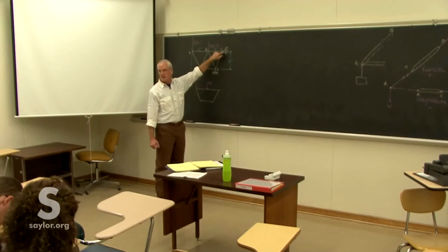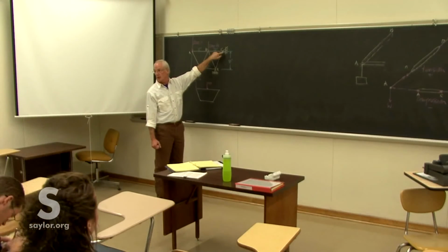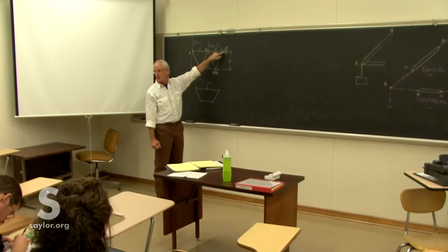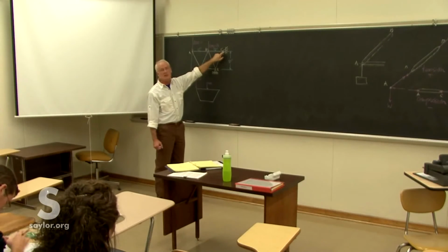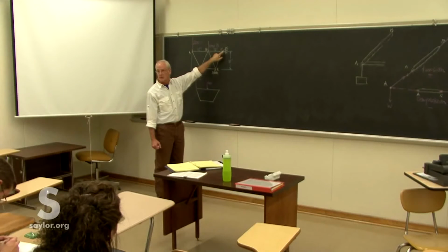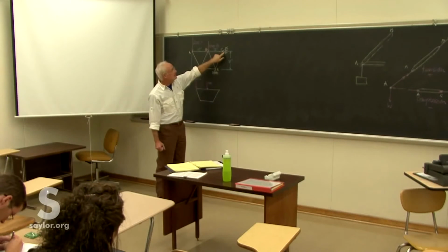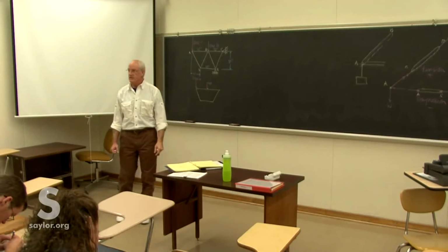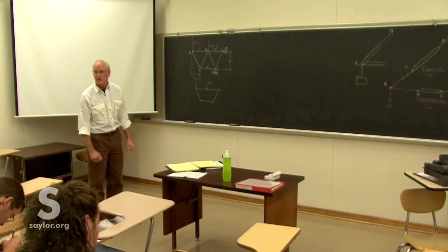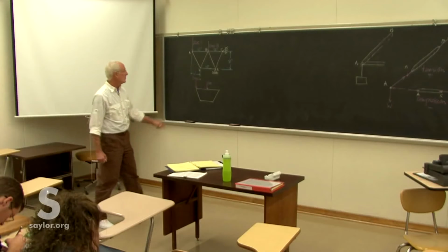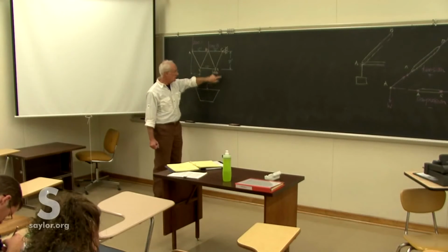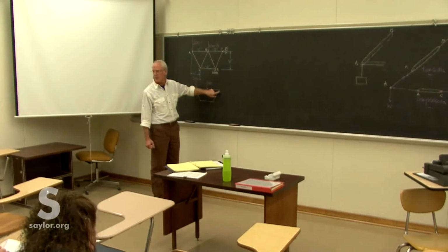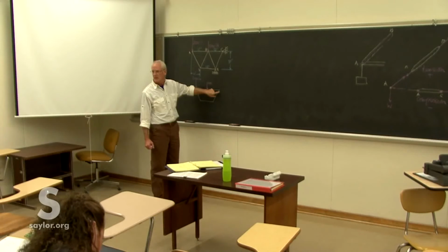This is a pin supported joint up here. And so what are the type of forces that a pin support can exert? Remember that the attachment itself is securely mounted on something, maybe a cliff or another building or something. So if I take out that support and put in its reactions, what do I put? Force in the X and Y direction.